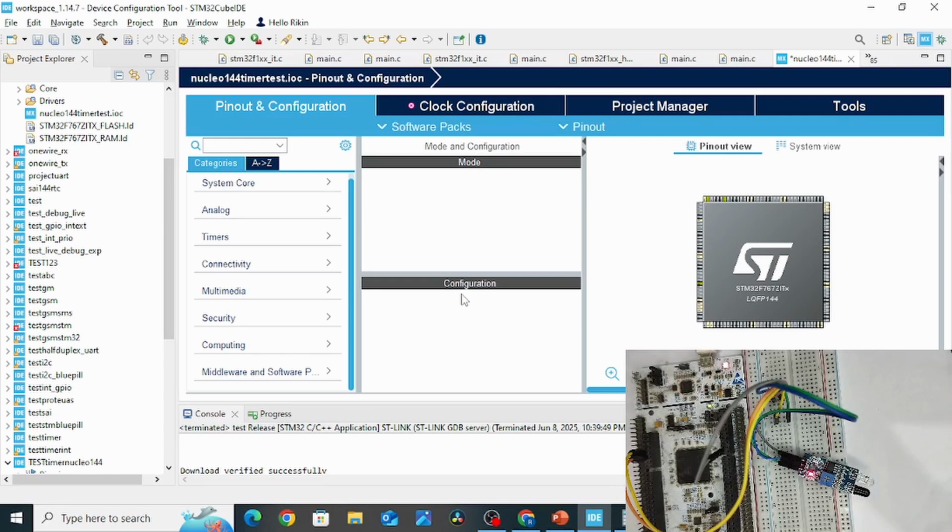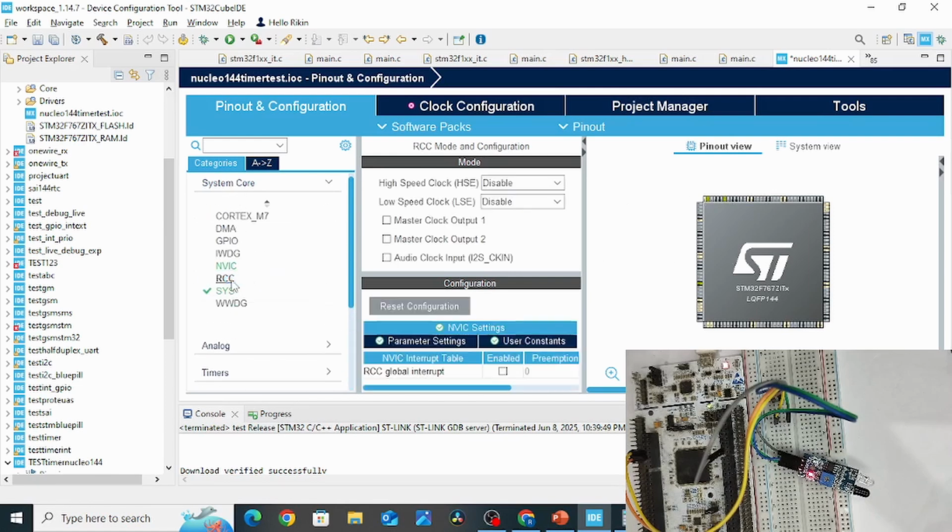Okay, along with this, to demonstrate the ongoing task, we are using UART. On UART we will display a continuous message, and from that message you can understand that some continuous operation is ongoing, and along with this the board will also perform its task, right? So let us say after clearing all the pins, first of all, let us connect these crystals in RCC. Okay, now let us choose the timer.